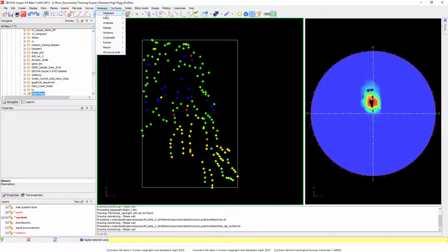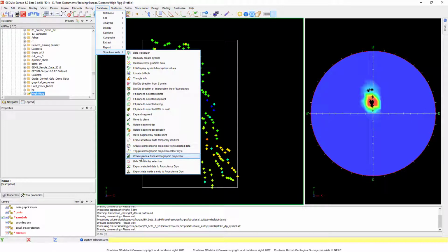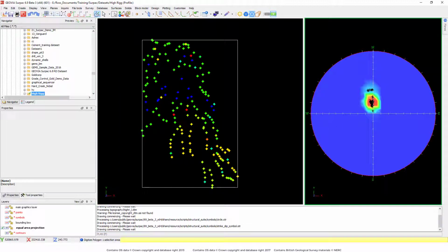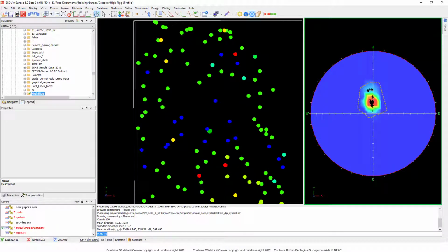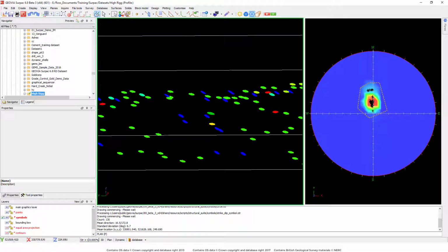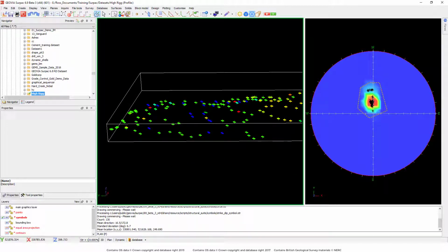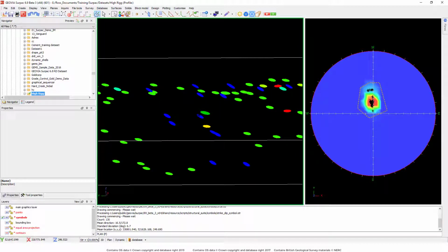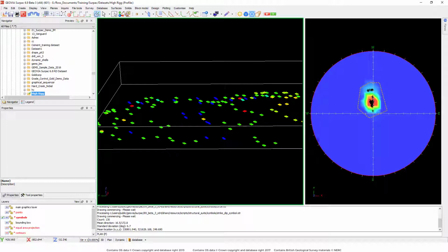What you can also do is, with the stereograph tools, you can also create a single plane from the collection of samples that you've got on here. So this will essentially create a best fit plane of all the samples on your StereoNet. And what that has done is it will have created, if you see this symbol here, this is below the topography, and out of those samples that I've selected inside this polygon, that essentially is the best fit sample that represents the general trend of all of those samples within that polygon.